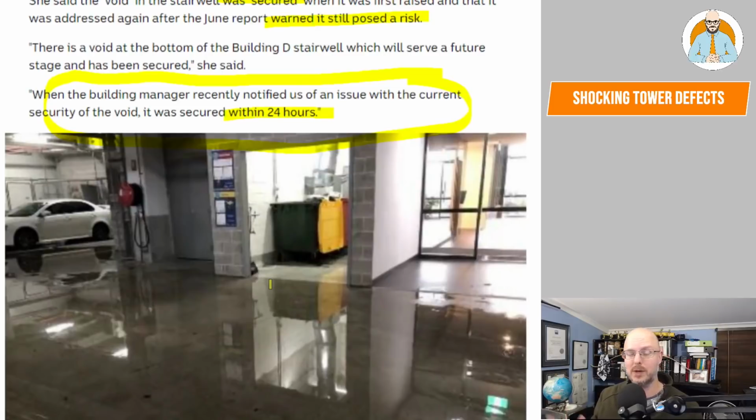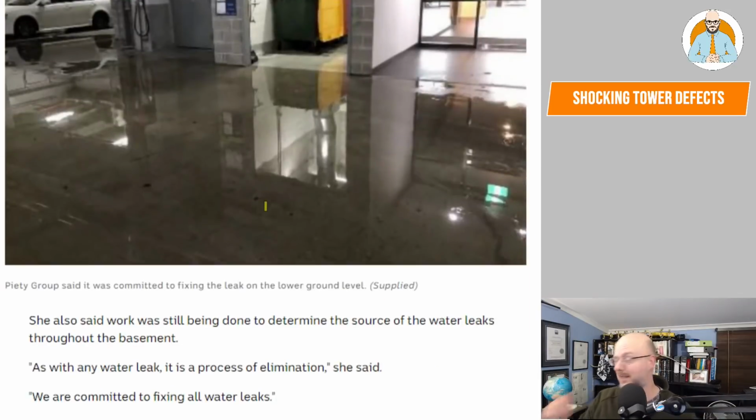Okay, the issue is when you're doing a construction project, you traditionally have a bank guarantee. You've got two of them. And what you do is you give one back after a certain period, and another one when you hit practical completion, and one after the end of the defects liability period. So you can draw upon that if you need it. If there are any defects, you've got money set aside, or you can have retentions and these type of things.